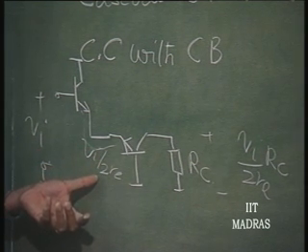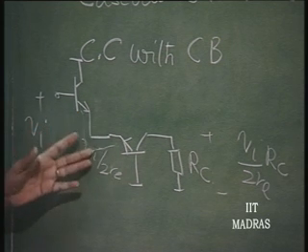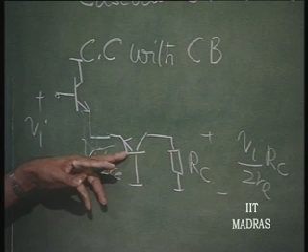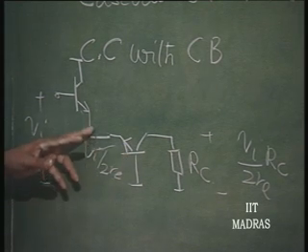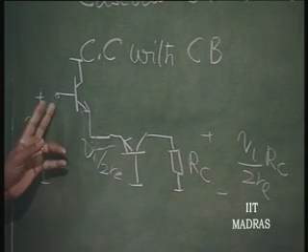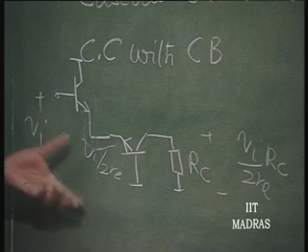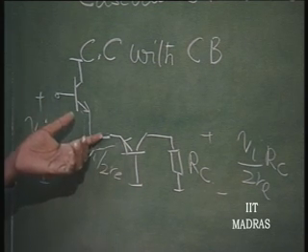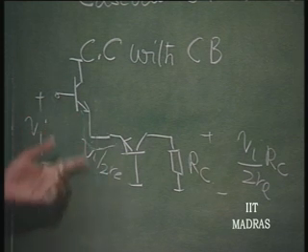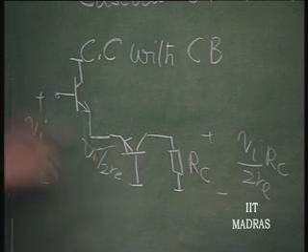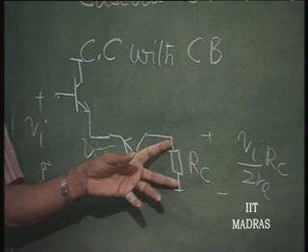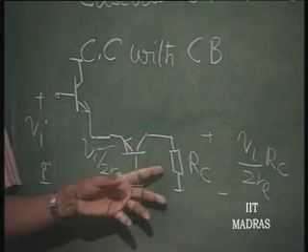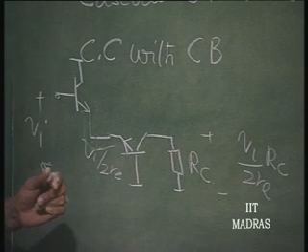Okay. So, the impedance level here is Re. If there is a capacitance, this Re is very small and it is shunted by another Re on the other side. So, Re by 2. Okay. So, it is very low. So, the time constant here is very low. Okay. So, the time constant at this intermediate point is very low. Okay. This is common base anyway, this is Rc and Cb dash C. Okay. That time constant also is very low.